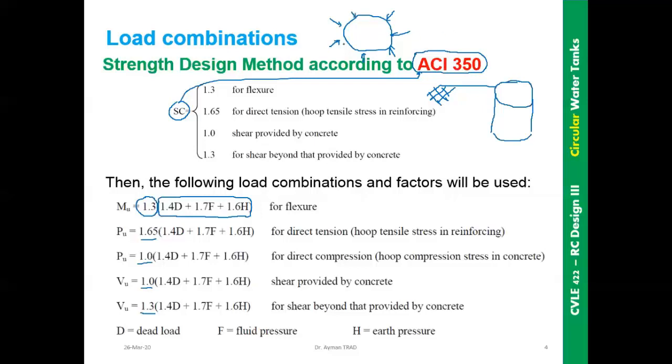So this is the soil pressure from outside to inside. If instead I have fluid pressure from inside to outside, in this case on the right I have the sanitary coefficient, so the combination has to be multiplied by 1.65. Here the combination is multiplied by 1, direct compression. So surely this case will be the worst.